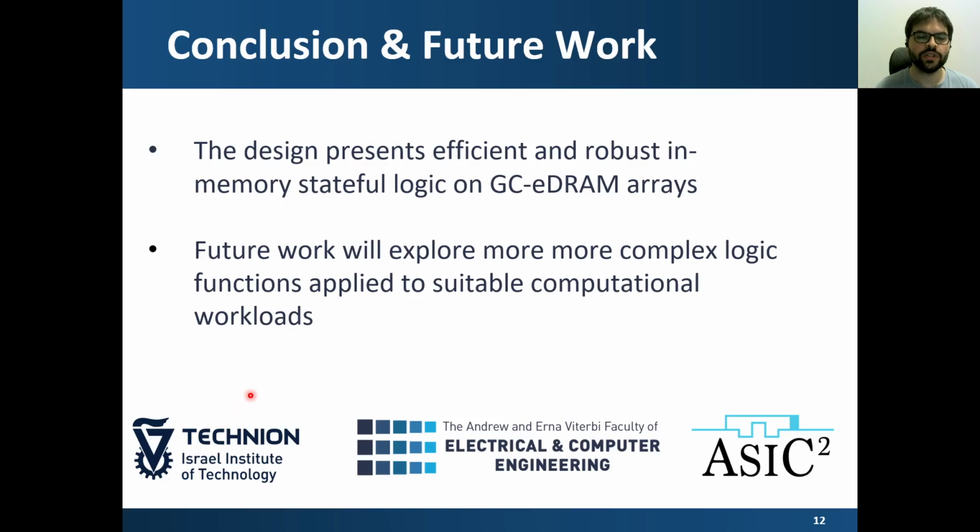To conclude, we showed the design of in-memory logic using stateful logic in GC eDRAM arrays, and we showed that it's robust and showed its principle. For future work, we plan to explore more complex logic operations using these logic gates as building blocks, and we will show how this idea can be applied to suitable computational workloads, and we'll show the performance benefit of using these operations. Thank you.